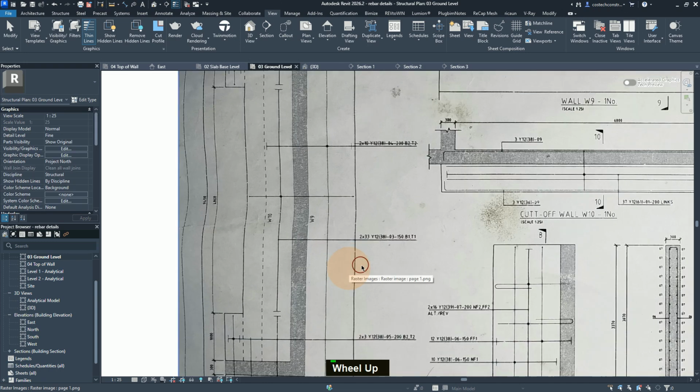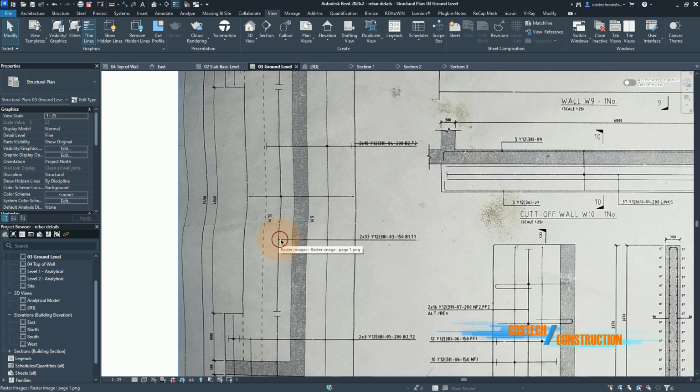So the next Rebar set we have is this one. So we see that it is 2 times 33 by 12, 38 for the shape code, and the bar mark is 03. Spacing is 150, B1 T1 layer. And if we go with it, we see that it spans from here, just before where the edge of the 400 was.